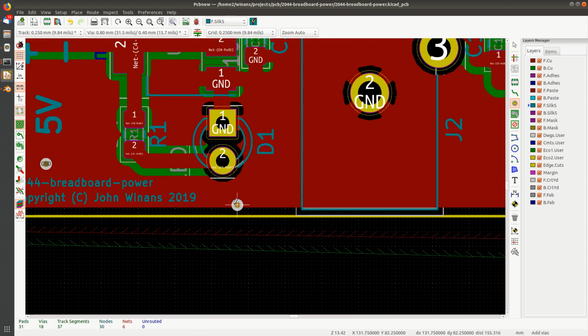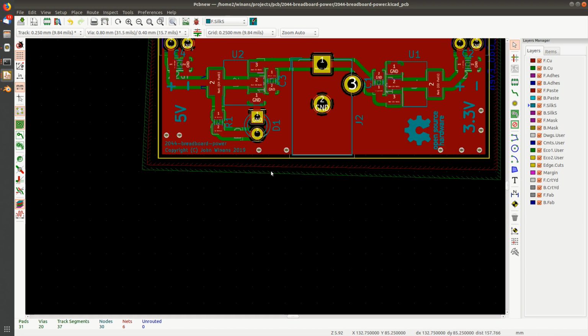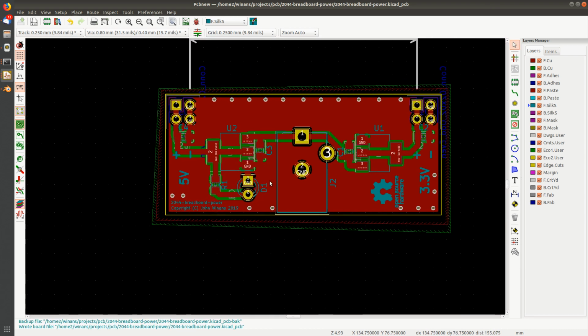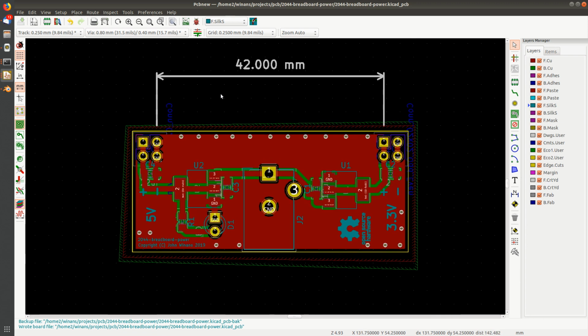I'll just put a couple more over here, maybe one there and one here, and we'll call it a day. All right, save. Now, if you go to OshPark, you're done. You save this file, and you can send them the KiCad file, this PCB file, and they will give you a board. Other ones need Gerbers and stuff. That's another video. I suppose I'm pretty cocky thinking I'm done.